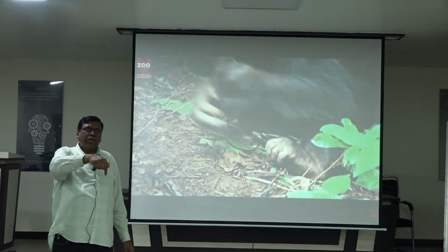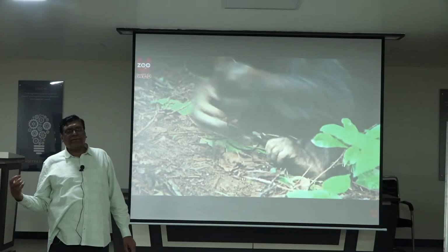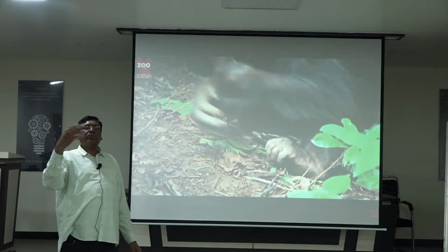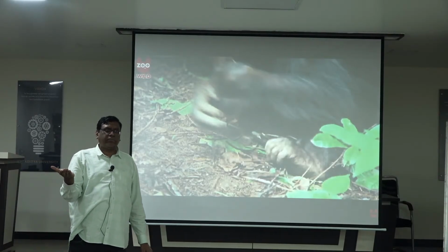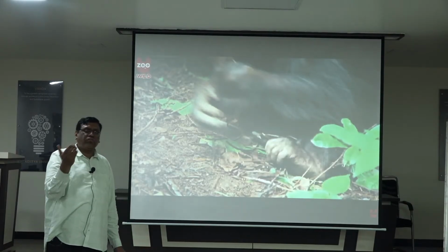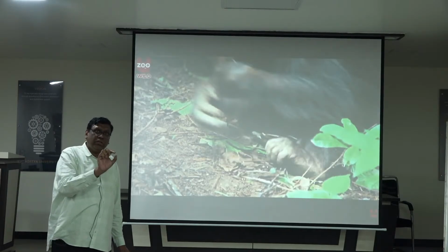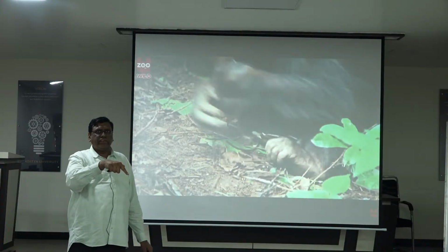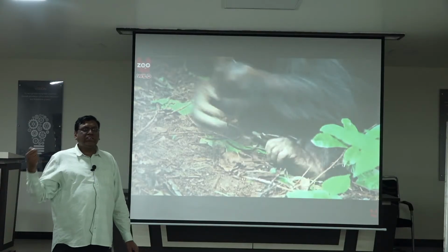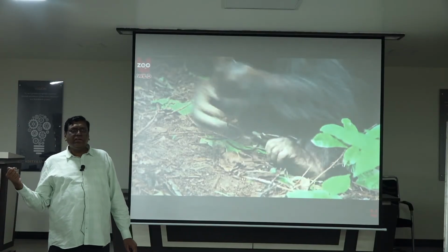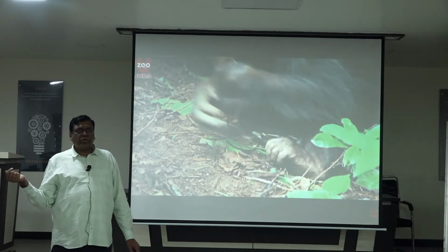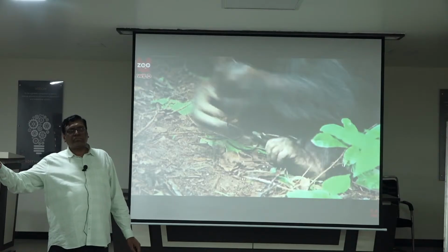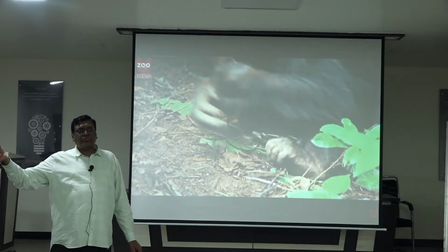Then I will shift out the internal node data. It will be captured into the flops again when I give one clock cycle. Then we do the shifting out. Previously we did the shifting in, and now we are shifting out the data from the primary output. At that time, the internal node data will come out from the flops.